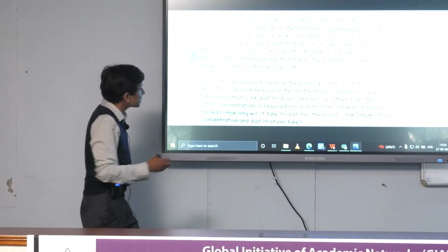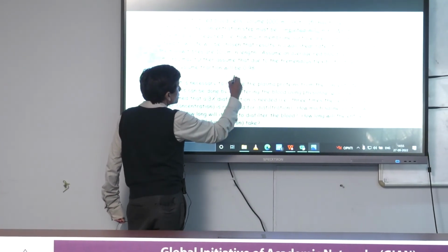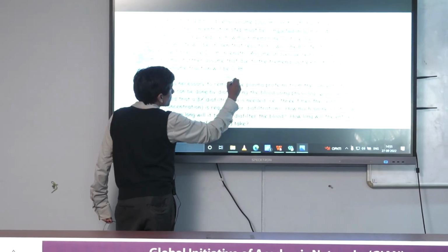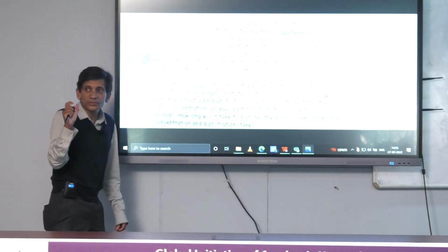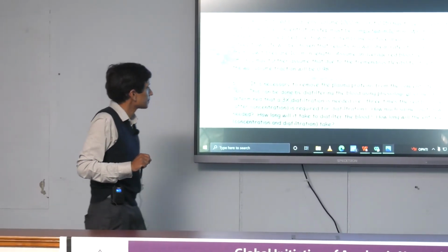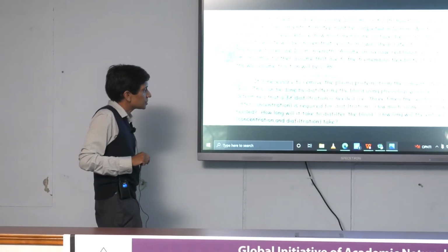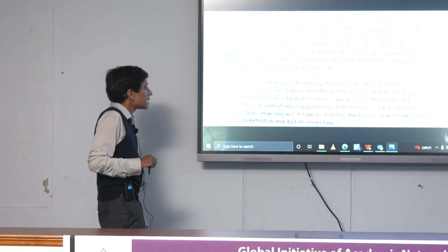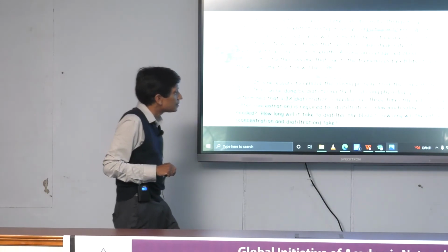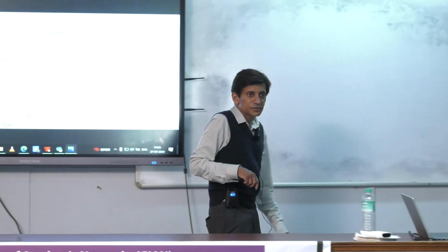You have determined that a 3x diafiltration, in other words, this is 3 diavolumes, okay? 3x diafiltration means 3 diavolumes, 3 times your feed volume, okay? Is needed. 3 times the red blood cell volume after concentration is required for diafiltration. How much saline will be needed, and how long will it take to diafilter the blood? How long will the entire process, concentration and diafiltration, take?